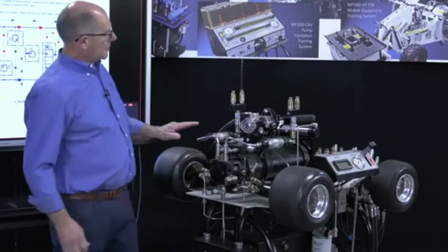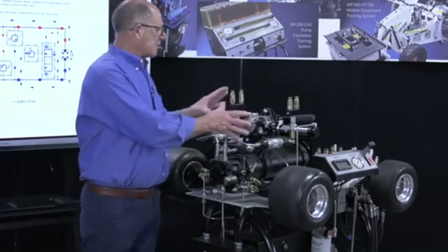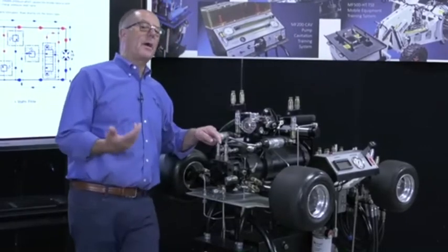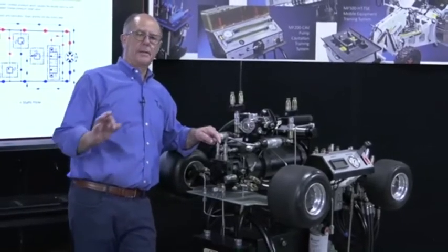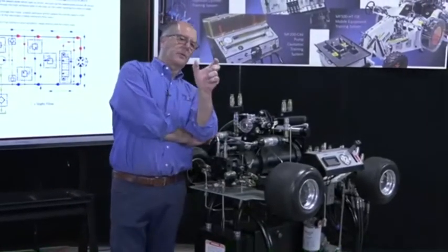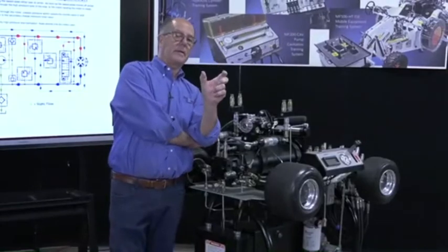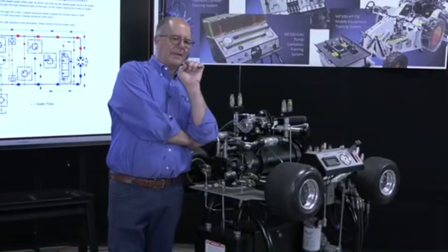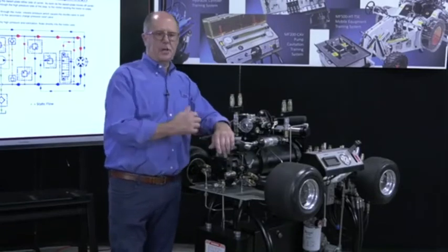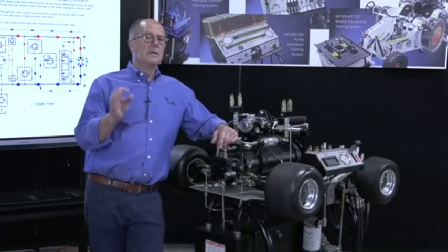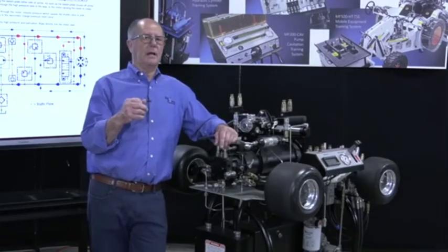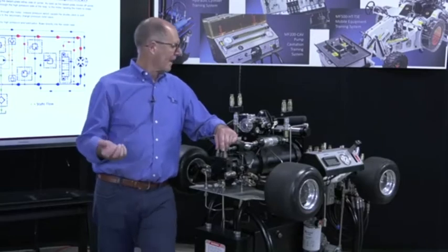All right. So basically, these are pretty much fixed from the factory. A lot of these heavy duty transmissions have main pressure relief valves that are non-adjustable. They are fixed. Usually if you take the cartridge out and it's fixed, you'll be able to read the pressure setting of the valve either on the side of the valve, or as a number stamped into the end cap of the valve. For example, if it's got a 50 stamped into the end cap, just add 2 zeros on the end, and it's typically a 5,000 PSI relief valve.